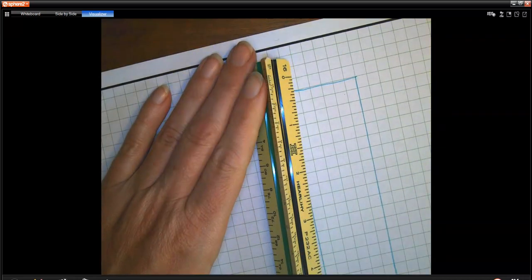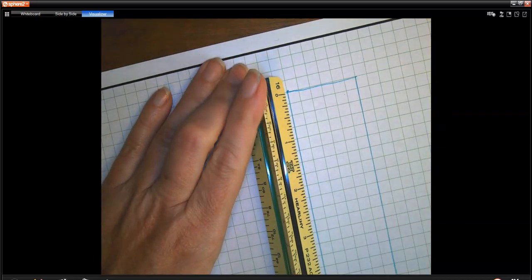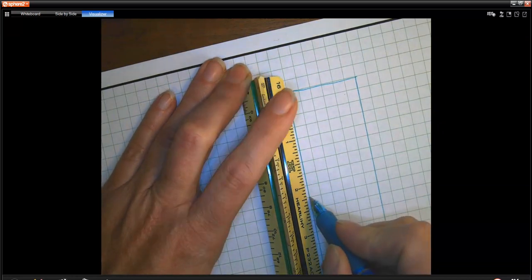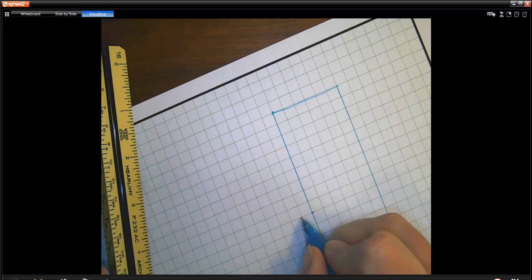All right, so we've got to do a little bit of math here. So you've got 4.5 inches here, 3 3/4 here. So we've got to look at the difference for that and lay that out. A lot of times what I'll do is just find the center. So the center of 4.5 would be 9 blocks. So that's also 2 1/4. All right, so this is the center. So I can go ahead and lay out my center line.